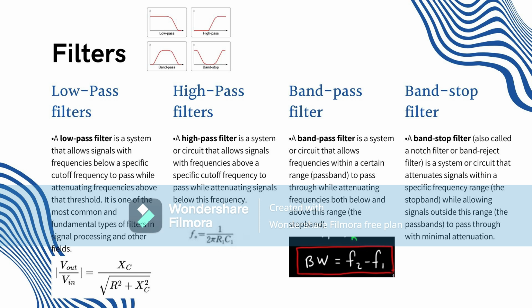it can eliminate hums and rumbles from audio signals. It can boost high frequency components and improve clarity in music or recordings. For communication, it removes low frequency components or DC bias from modulated signals, and eliminates low frequency interference caused by nearby electrical equipment, and removes low frequency sounds like wind noise from speech recordings.